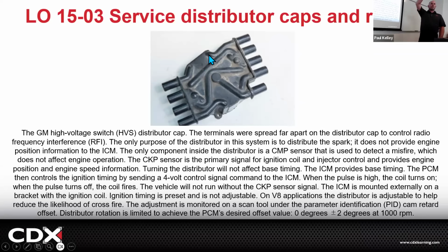Okay. Then when you go to slide it back in, you have to have your engine turned, with your little screwdriver in the spark plug hole or whatever, to cylinder number 1 at TDC. You remember that? Cylinder number 1 goes to top dead center, top dead center of compression, not exhaust. If it's at top dead center of cylinder 1 on compression, isn't that when the spark should occur? Good. So we're going to make sure that that's the case on cylinder 1, and that this pointer is pointing to cylinder 1 for that rotor. And then boom, you drop the distributor in, and your base timing, you're close.